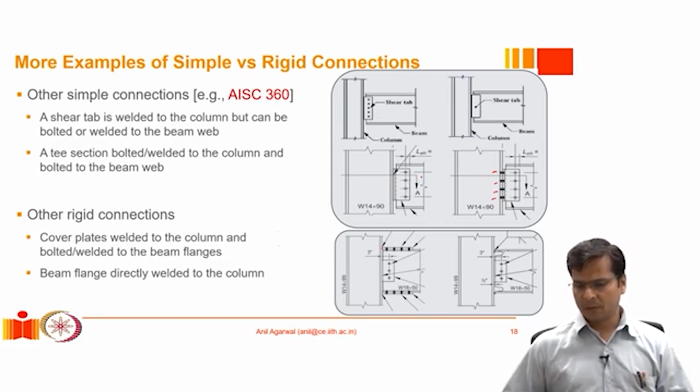Okay. Here also, in addition to that, you might notice that we require separate provision for resisting shear, which we did not require typically in an end plate connection. The reason for that is because these connections are very localized near the flanges, and the shear force demand at the flanges is very small, and plus we sometimes have to create these kind of cuts. These cuts are access cuts so that we can weld around this area comfortably. So considering all of these, these parts cannot effectively transfer the shear force demand.